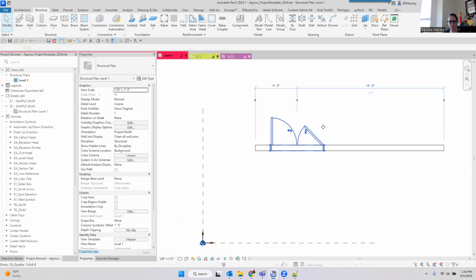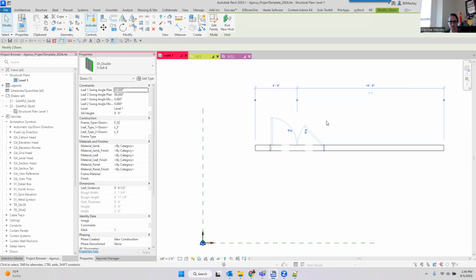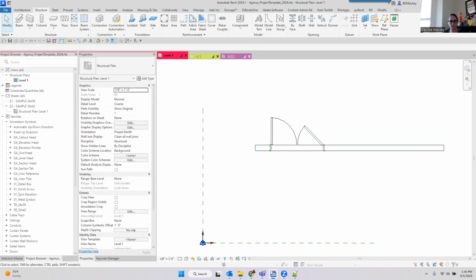The other thing for me on knowing when to use shared parameters is if I want to schedule it not necessarily for scheduling purposes, but for manipulation purposes. So I come through here, and a lot of my families, the materials are going to be shared parameters. Not because I ever plan on scheduling the materials on this stuff, but because I want to be able to change these values via a schedule. So I do need to make it a shared parameter to schedule it. If that's the case, I want to be able to manipulate it via a schedule. That needs to be a shared parameter. So hopefully that answers that question.